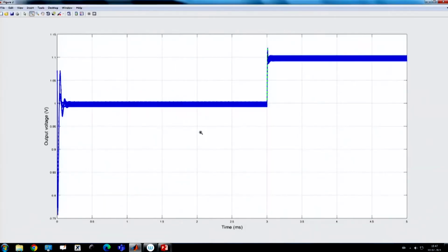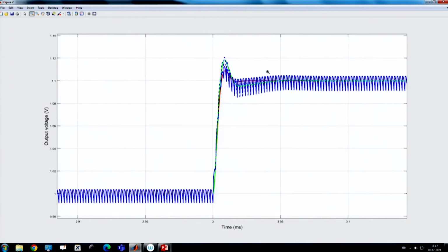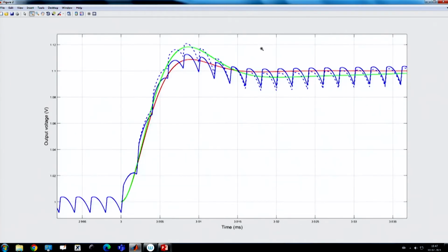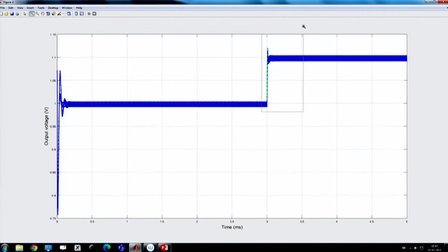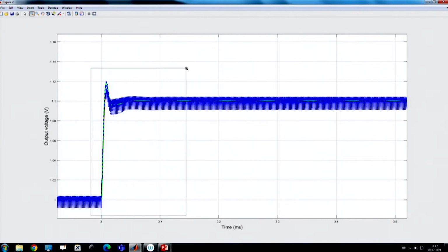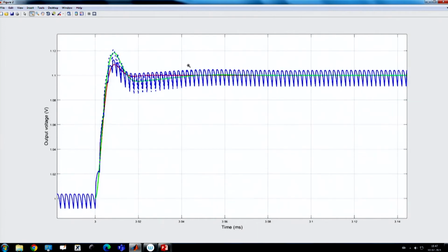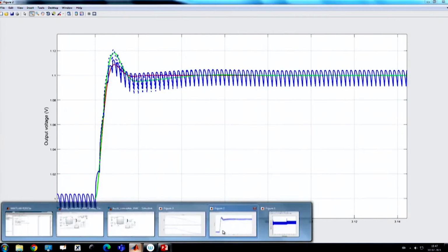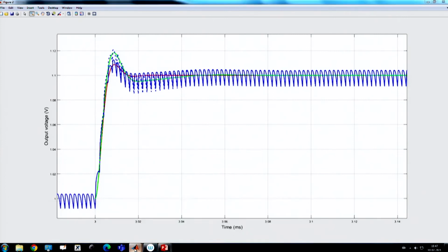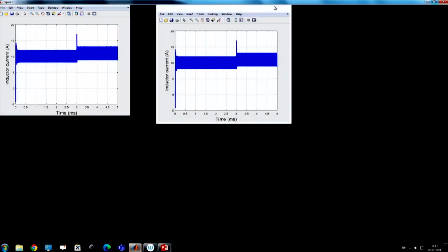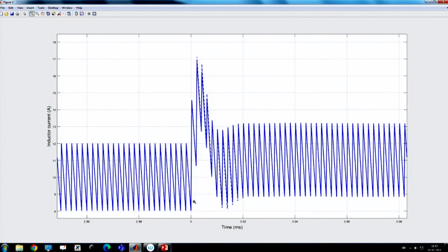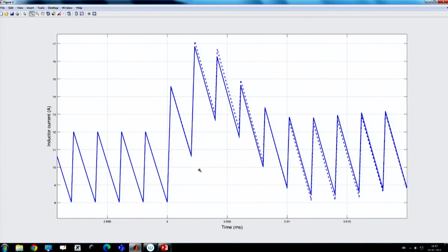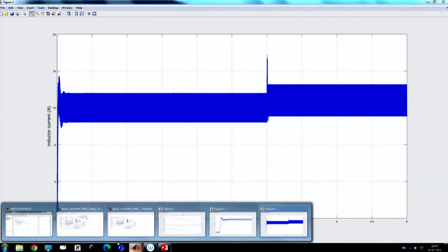Yes. So, it looks like the response of the converter does not change drastically. This is with the worst case scenario that we are compensating. That means, we are comparing exact cancellation with robust compensation, and there if you see the inductor current response, they are also very close. That means, we do not need to know exactly the value of the load resistance, they are quite matching.